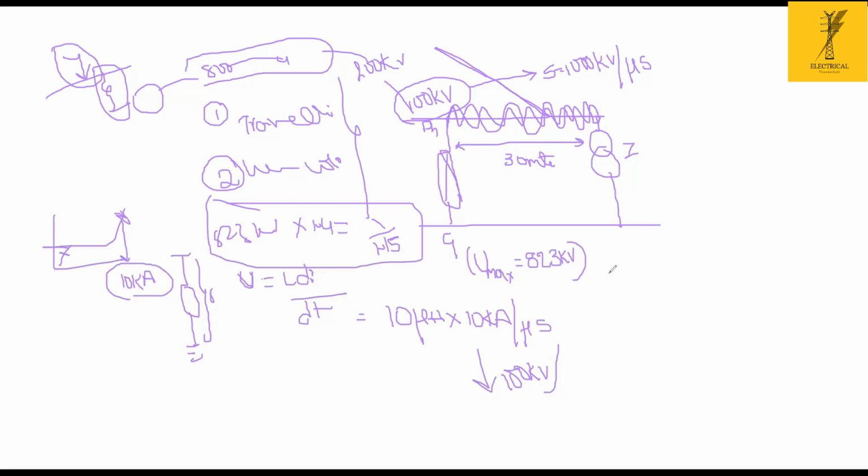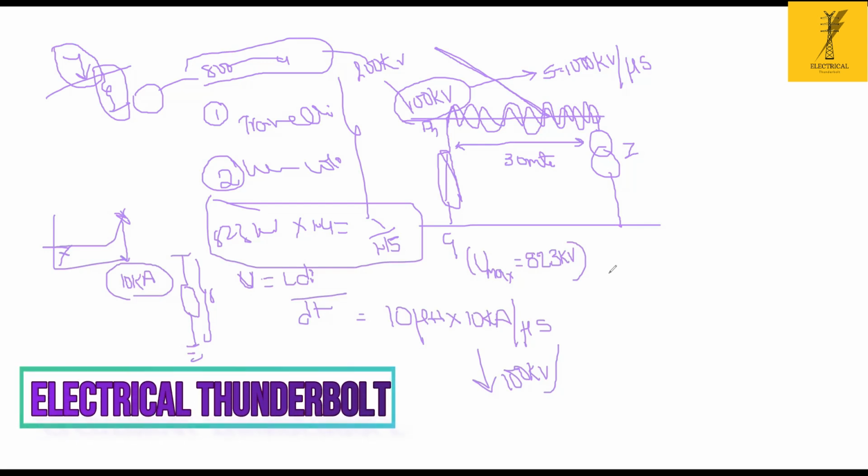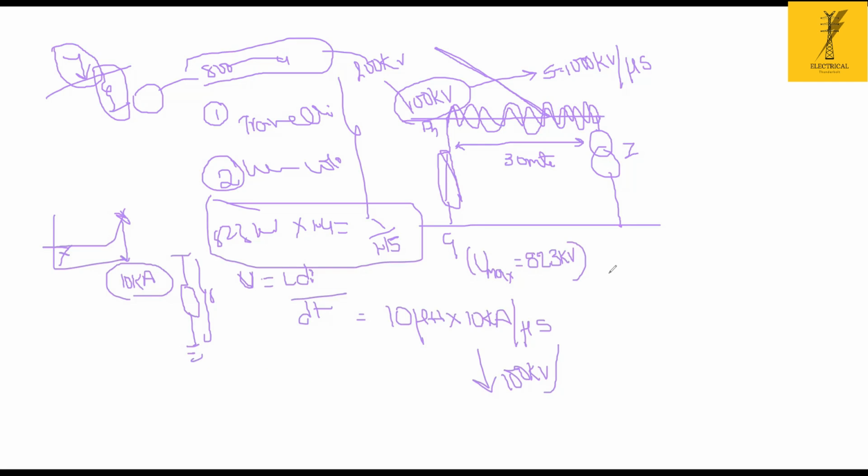I mean, in a simple way, when you are discharging this 10 kiloamps of current through my lightning arrestor in a single discharge, the energy accumulating there should not exceed the thermomechanical overstress limits of the metal oxide resistor inside my lightning arrestor.